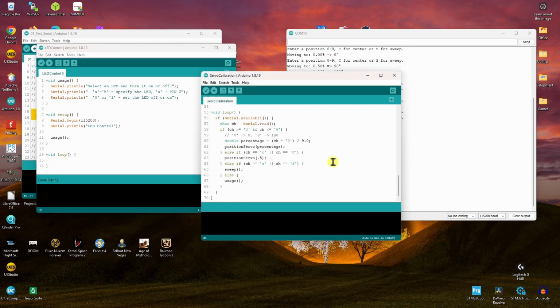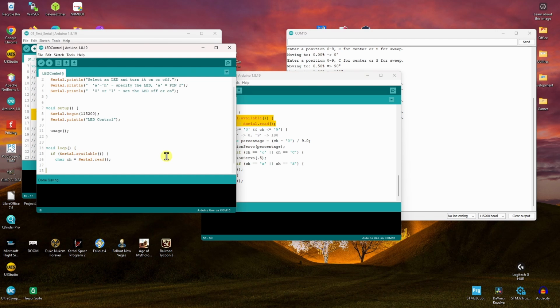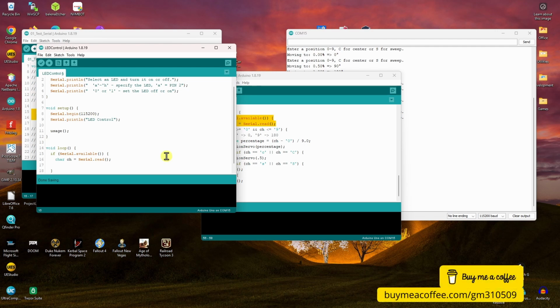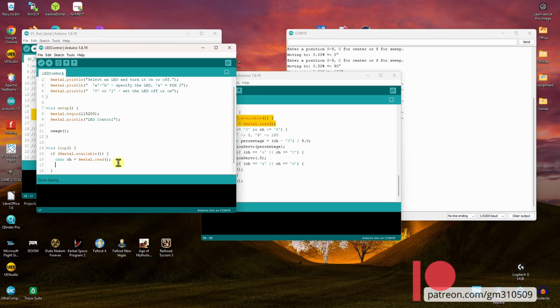Once again, we will want to check if there's something to do. And now this time, because we had 2-letter commands, we need to track which LED we're talking about and what operation we do, because as you would have seen here, one character was coming in at a time. So we can't really get 2 characters at once. You sort of can, but it doesn't really work that way. They come in one at a time. You can collect them up into chunks of 2 or more, and we'll look at that a bit later. But literally they're coming in one at a time, and so we need to deal with that situation.